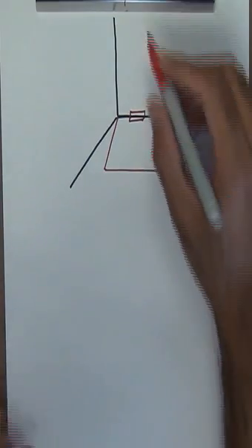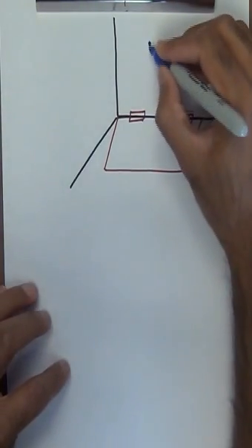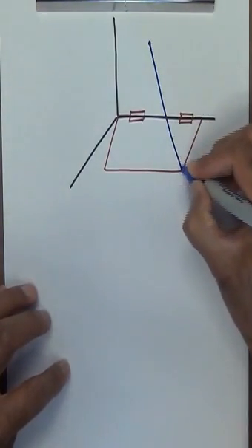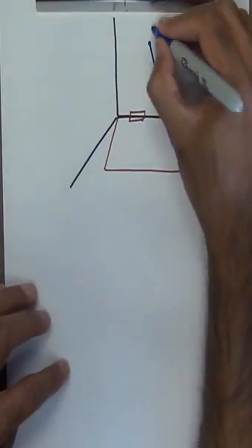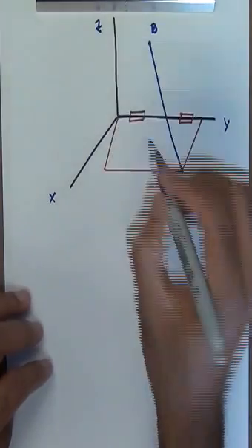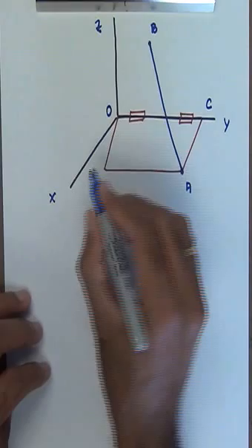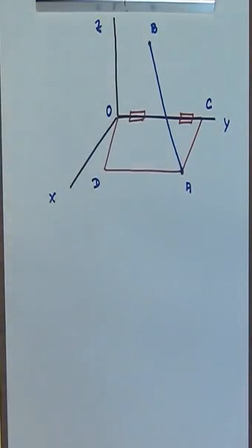And then I have a line joining the point A to the point B, which is where the force is running through. So this is A, this is B, this is first of all the y-axis, the x-axis, and the z-axis. Here is the origin, and then here is the point C, and then here is the point D. Alright, now we just want to set up the basis for finding moments about both the axes of interest that we are asked to find the moments about.